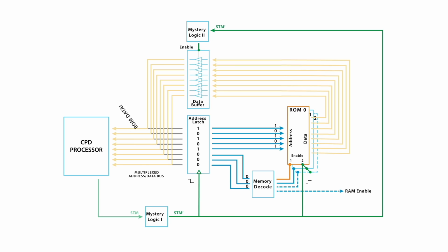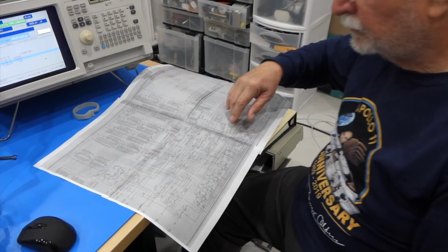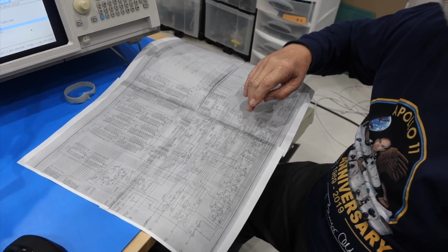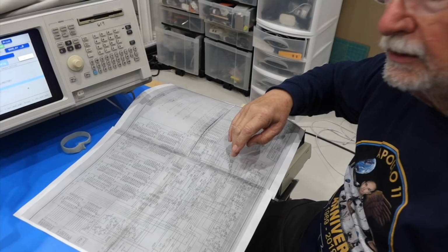Now that the data is on the bus, our processor can finally read it. So long story short, there are quite a few chips that could have failed in this chain and caused the problem. We have come to the conclusion that we don't think we read ROM. Right. So what's the next experiment?